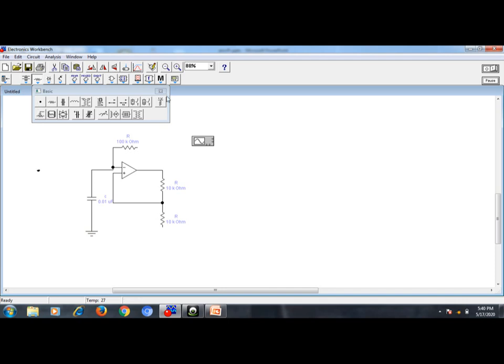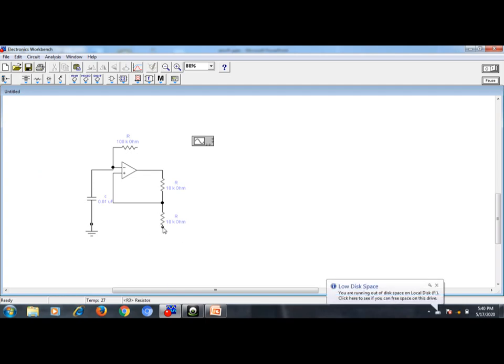So take this connector. After taking it, it will show the connection, and drag it and place it here. After placing this one, next the negative, the other end of this series resistance, is connected to this connector. Let us see, it is going to connect. Next, the other end of this feedback should be connected to pin number 6.